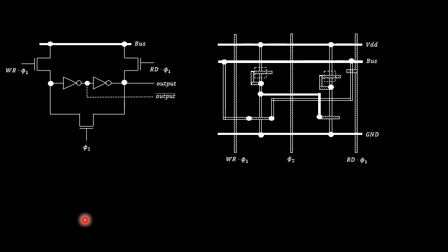So, before that, you are concentrating on the concept of refresh operation, wherein the dynamic memory cell demands a periodic refresh operation to be done. The advantage of performing the refresh operation is that I can retain the data as it is while performing the read operation. Whatever data is written in the capacitor in the form of a charge has to be read as it is. So in order to have the read operation done 100% perfectly, I have to concentrate upon the lapse of 1 millisecond of time duration. So it becomes a tedious job over there.